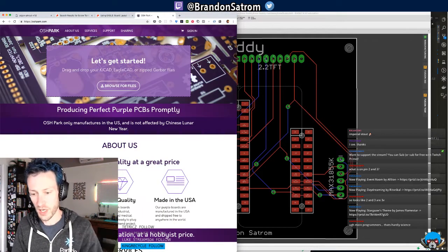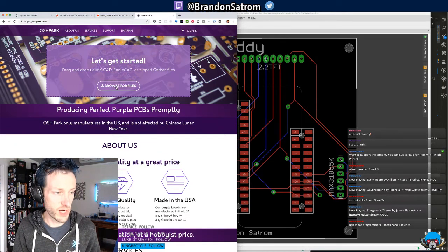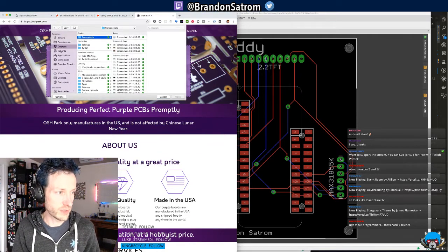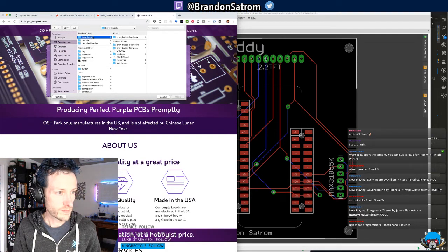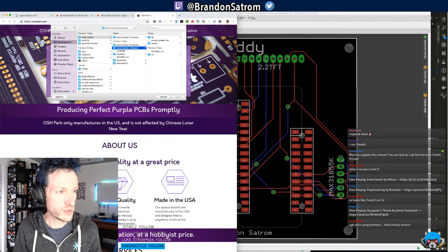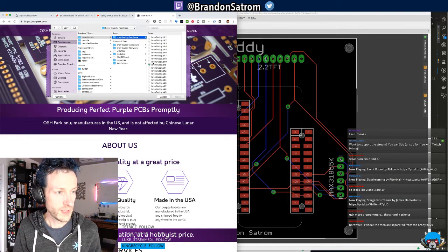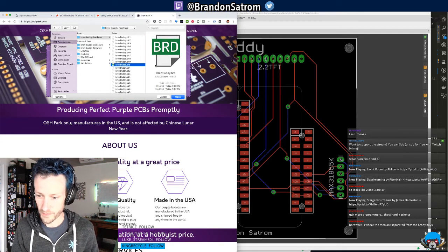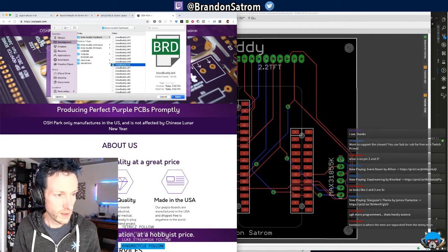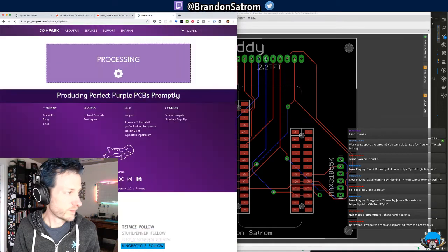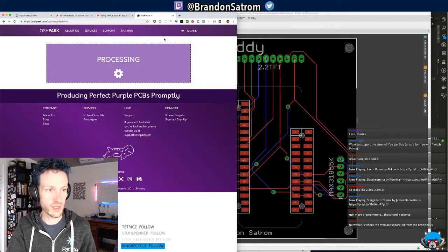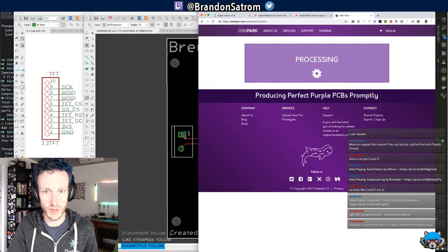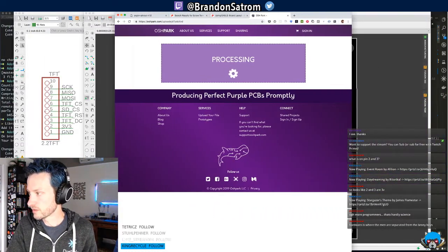So the way that OshPark works is you can actually just browse for a .brd file directly, which is the board format that Eagle uses. So if I go into hardware and then I go into .brd and then click open, and say uploading your design, this will actually take just a moment to process. Hopefully it won't give me any errors. I can show y'all what's going to happen here.